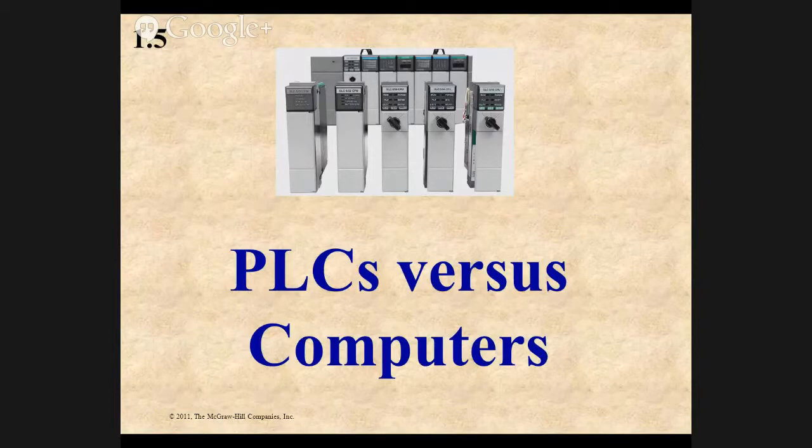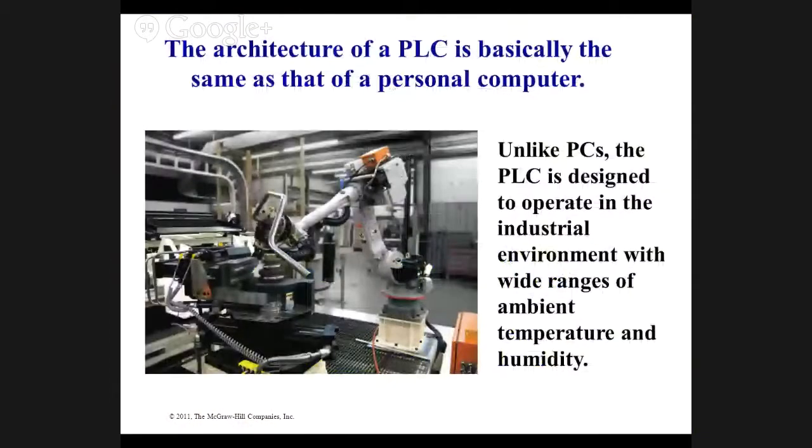So, PLCs versus computers. The architecture is basically the same. A PLC is just a small computer. The only difference is PLCs are designed to work in a harsh industrial environment. Oil, grease, high humidity, they're kind of battle hardened, where a PC would not last. In fact, you can buy industrial grade PCs and laptops to run in the industrial environment. They cost a lot more because they're designed to be a lot more rugged and have filters and stuff for the air and everything.